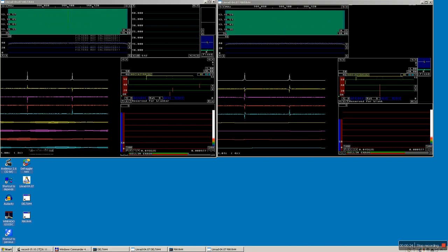White is power, yellow is I and magenta is Q from audio channel 1, and red and blue are I and Q for audio channel 2. There are 4 tracks which would contain strong signals, and we don't have any strong signals, only the discontinuity at the center, the center spur, and that doesn't matter.